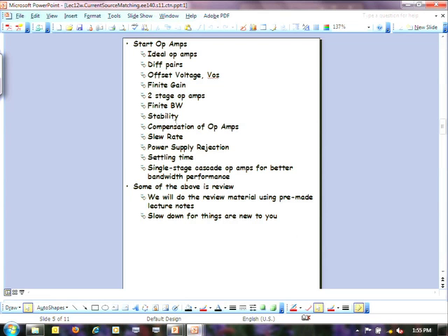And basically, the whole gain across this is going to be R sub I over R sub I plus RS times that voltage gain times R sub L over R sub L plus R naught, and that's the gain. So obviously, if Ri is infinite, this becomes 1.